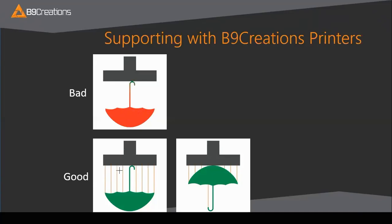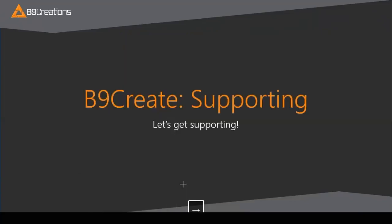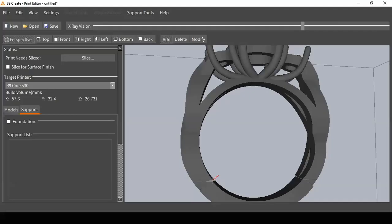These points are where it is necessary to add supports. The next graphics show the umbrella supported as is and then oriented differently and supported. As you can see, orientation can affect where your support placement is as well as the number of supports used. So while keeping what we just learned in mind, we're going to go back and finish completely supporting our model. All right, next we are going to add supports to this model at critical structural points so that it can be printed properly.